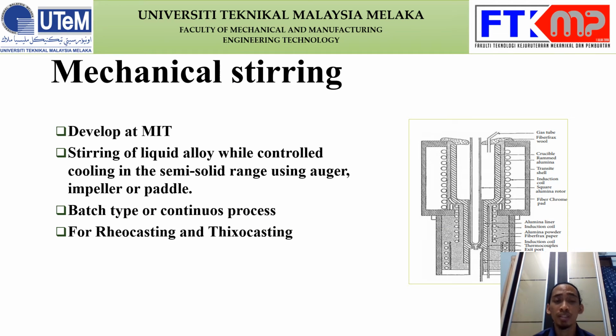Mechanical stirring was developed at MIT. It involves stirring the liquid alloy while controlling cooling in the semi-solid range, using an agitator, impeller, and paddle. It is a batch or continuous process, used for rheocasting and thixocasting processes.